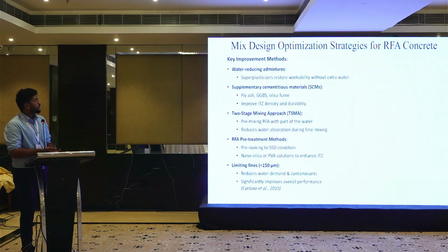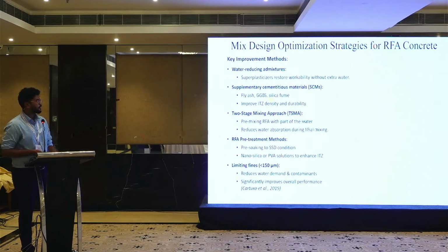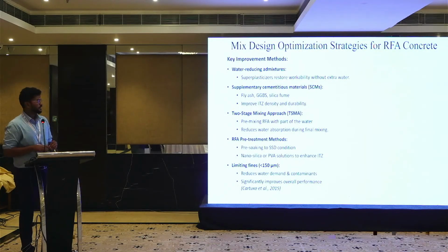So for that we are coming up with solutions. Key improvement methods: water-reducing admixtures, where we can add a superplasticizer to restore workability. Supplementary cementitious materials like fly ash, GGBS, and silica fume can improve ITZ density and durability. And the two-stage mixing approach, TSMA,